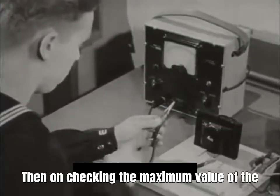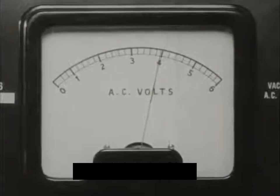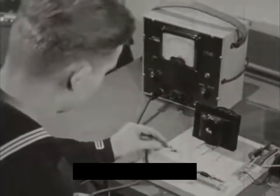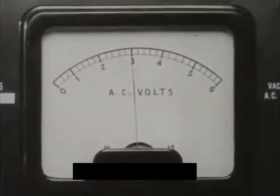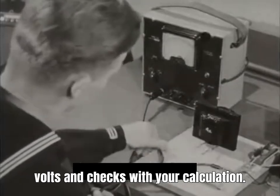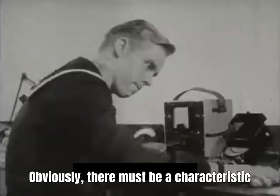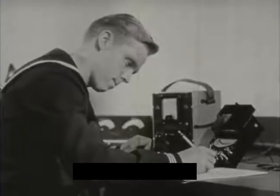Then, on checking the maximum value of the voltage drop across the inductance, you find a drop of 4 volts. Checking the voltage drop across the resistor, you find a drop of 3 volts. This makes a total drop of 7 volts and checks with your calculation. Now you measure the source voltage, expecting it to read 7 volts. But it reads 5 volts. Obviously, there must be a characteristic concerning AC to which DC formulas do not apply.